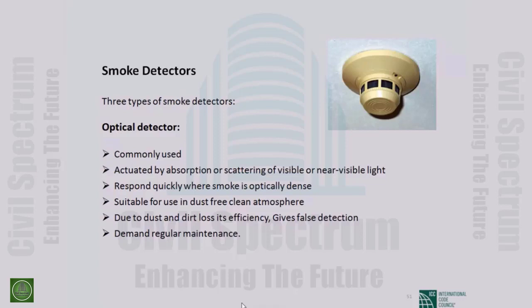So for smoke detectors, particularly in our country, where we are habituated to very natural air velocity, natural air flow, and we always have our rooms with a very high velocity ceiling fan below, in that case there is every chance of wrong detection. So you have to be careful about fitting this smoke detector. Their location is very important.